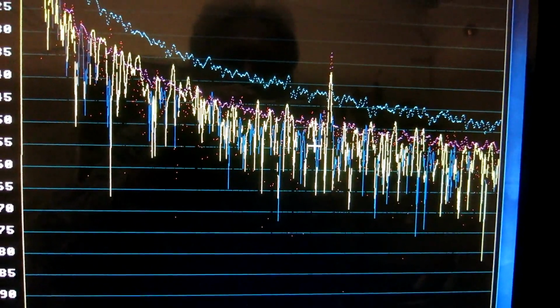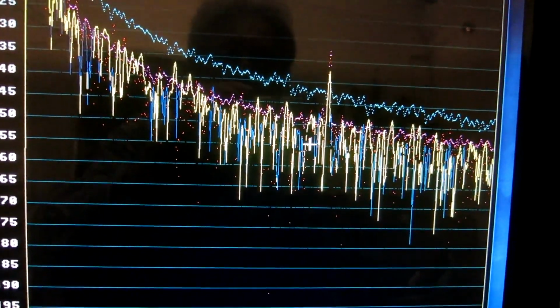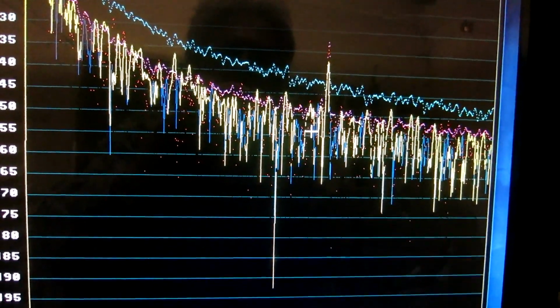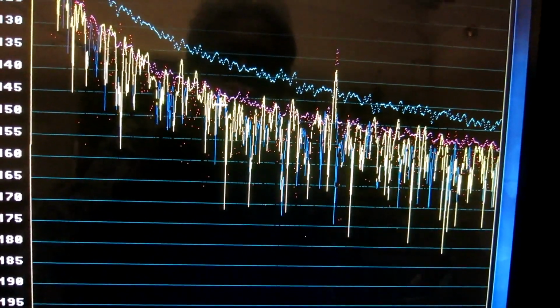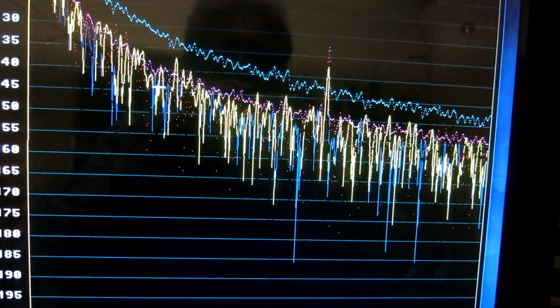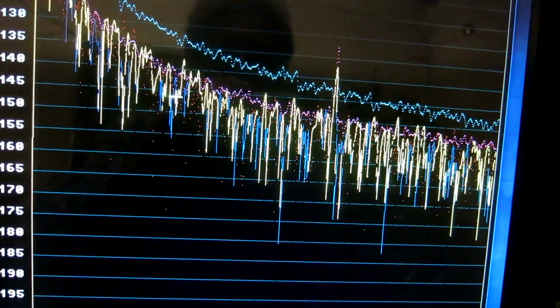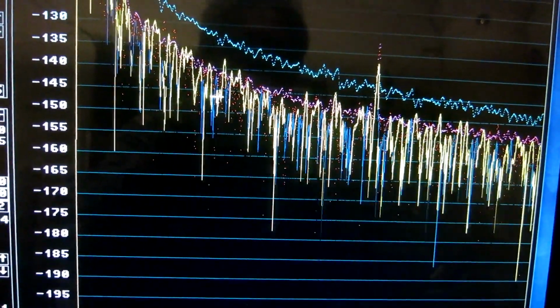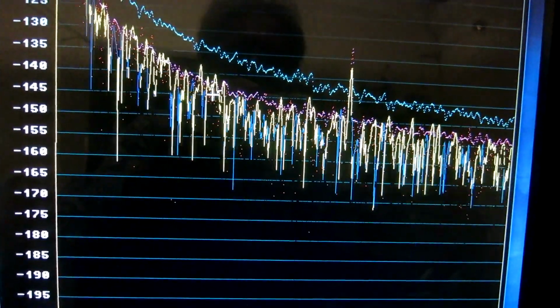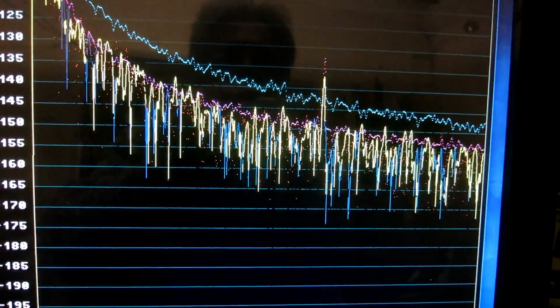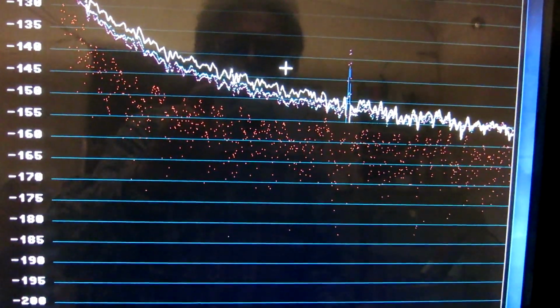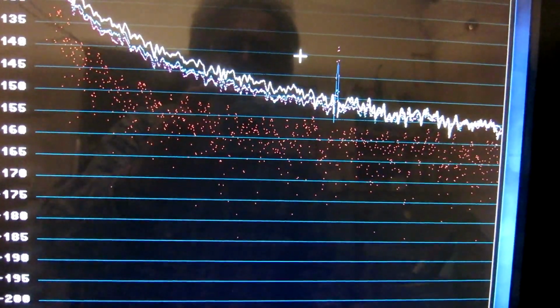And maybe I would have to wait for 6 hours or even more, because at very close range the signal to noise ratio of the system degrades because of the phase noise of my local oscillators. For amplitude noise, it is a little bit better.